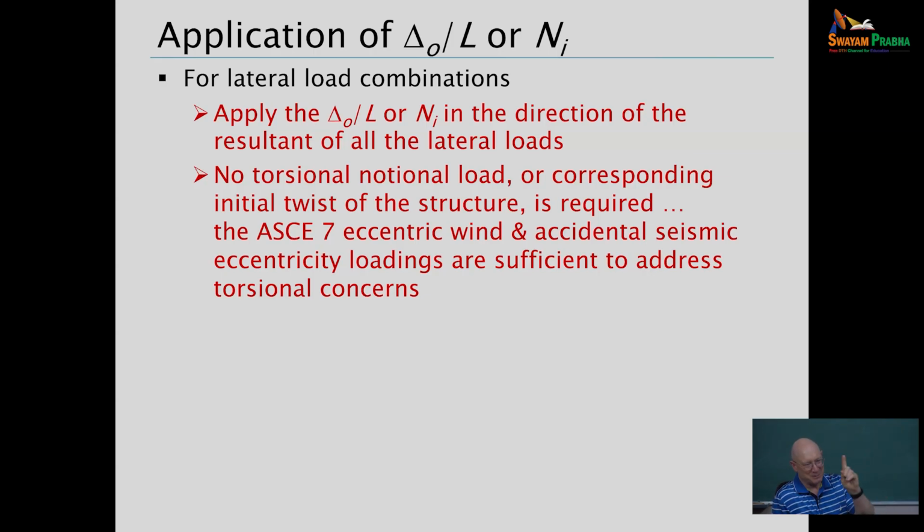You better put the notional load on with the lateral load, in the direction that would, of course, increase the lateral loading effects. But you don't have to do torsional notional lateral load ever. Your wind and seismic eccentricities will give you plenty of torsional effects.